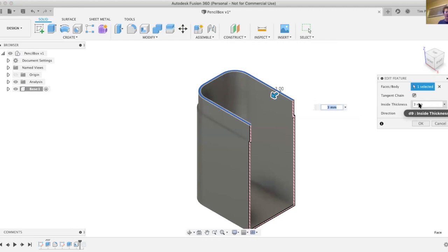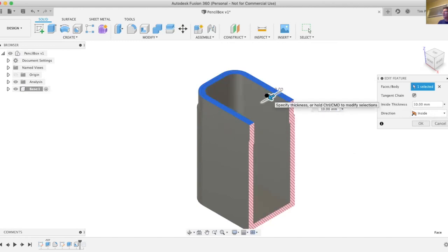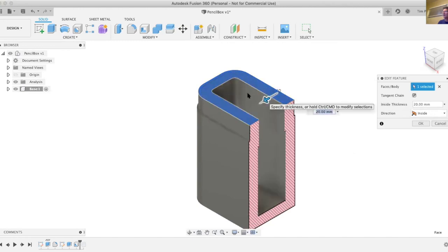It's a very, very useful tool. You can put in complex tapers, all kinds of fillets, etc., and then shell it out at the appropriate time. And which surface did you use to then say 3mm offset, and how did you keep it from going through to the base? So basically what it did here is all the surfaces except the surface I selected is a surface to be removed entirely,